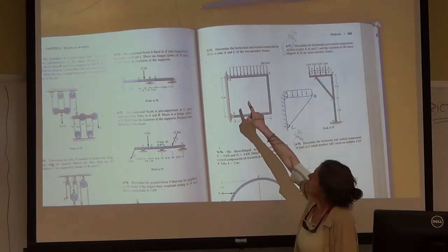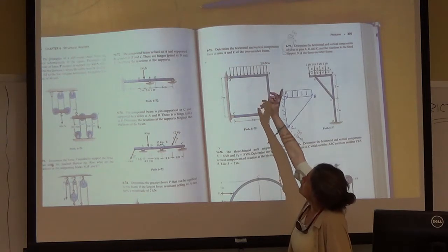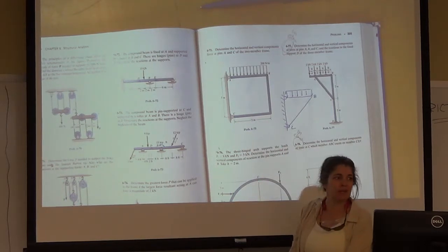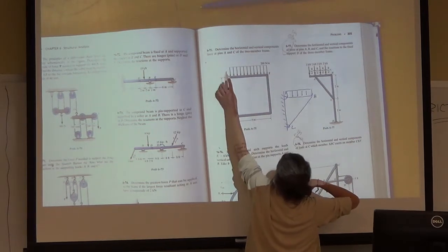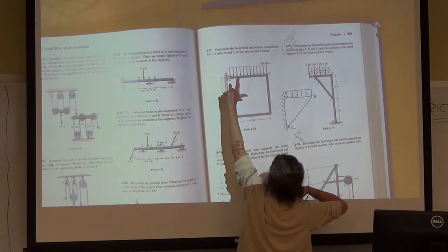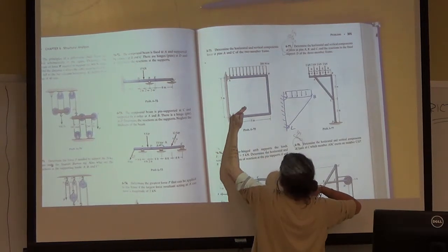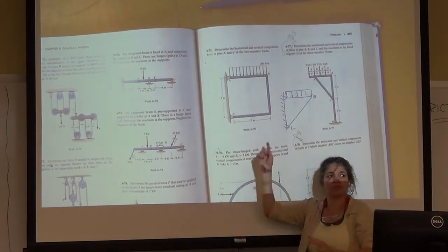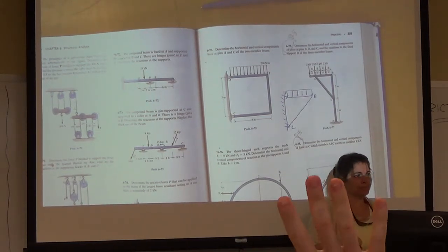The question asks for us to find the horizontal and vertical components of the forces in pin A and C, which they're actually asking you for. What are the reactions at A? What are the reactions at C? A, you're telling me because this is not a 2 force member, there's an AX and AY because it's a pin. This is a 2 force member, which means the loading goes straight from C to B, which is 1 unknown. So we have a total of 3 unknowns. It's a 2D problem. How many free body diagrams do you need? 1. Matt.